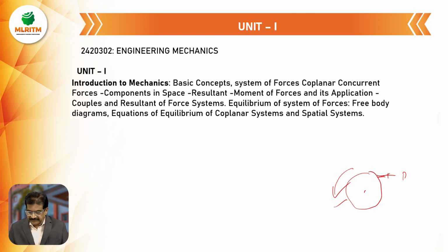The last one is the free body diagram. Free body diagram means we have to sketch the given diagram, showing all the active forces and inactive forces, remove the supports, and consider the geometrical angles and geometrical dimensions. That is called the free body diagram.